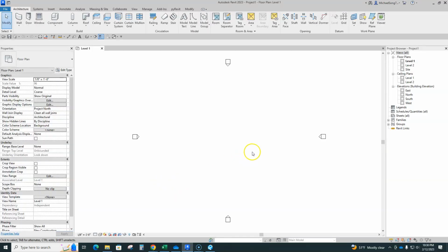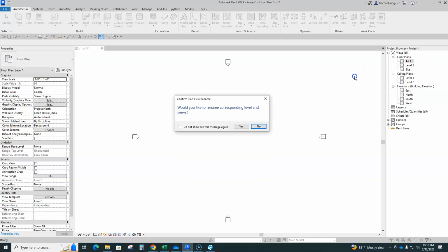You'll notice that it starts you off in Level 1. Of course, we can rename this. Level 1 could be, for instance, ground level or floor plan level. For us, let's just start with a floor plan. This is a 2-story project, so we will change Level 1. You long click on that and change it to, let's say, First. I like to call it Finished Floor. That's the surface you'll be standing on if you're inside the house.